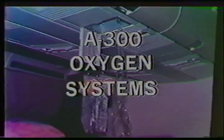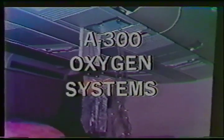All oxygen on the A300 is chemical, with the exception of that used in the flight deck. First aid oxygen is administered from the Aviox chemical bottles located at each flight attendant jump seat. Emergency oxygen is also chemical. Each passenger service compartment houses a chemical oxygen canister which will emit 4 liters for 10 minutes. In a decompression, each compartment will open automatically. Masks must be extended fully for oxygen to flow.